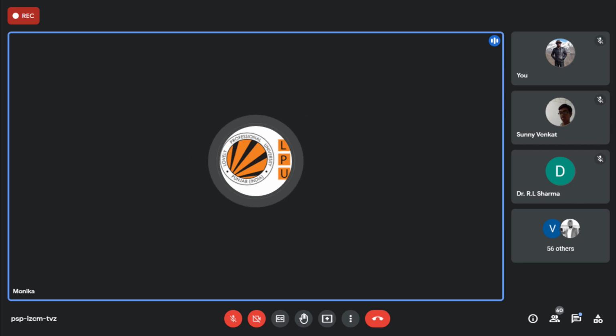So a much better thing is, on the third day, if you are able to complete the work at half time, leave that work and do not start the next activity without preparation. Just leave that half day as a gap to prepare for the next activity you are going to start. Maybe you are going to start with the column reinforcement mesh. So if you are going to start with that, just make sure you have all the resources at the site. You have all the requirement of resources available. Then only start with another activity.